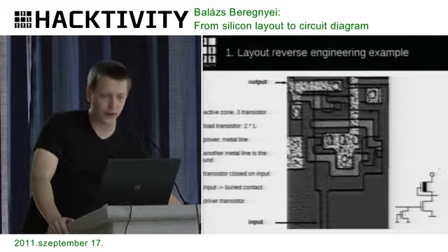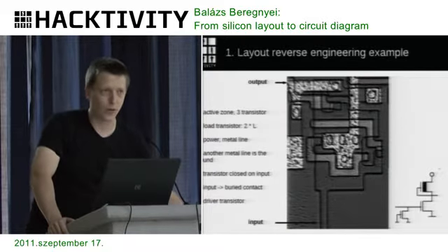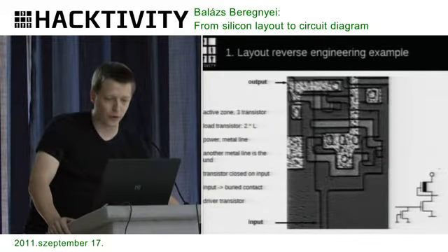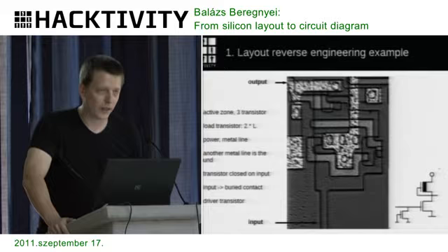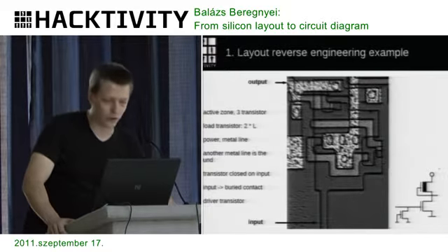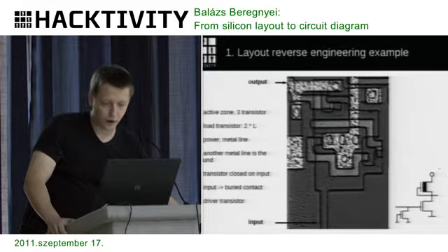And that transistor here has double bandwidth, so it has to be the power switching transistor, which means that this band here is a power supply, but it also has to have a ground somewhere, meaning that this aluminium foil is the ground.